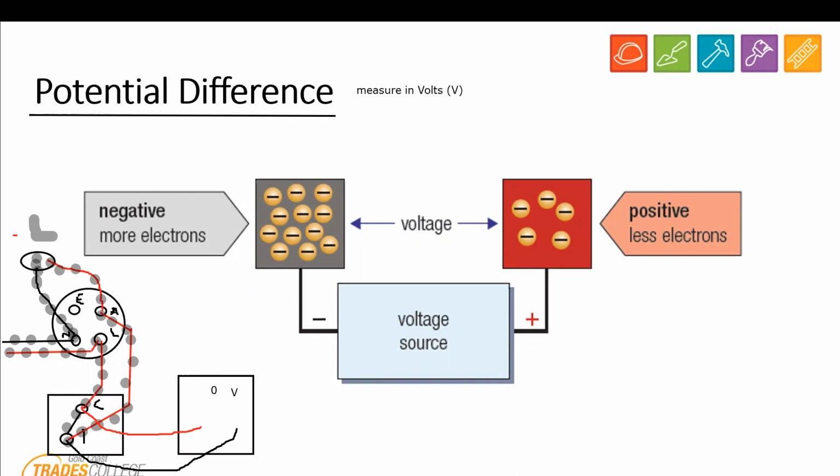Let's get rid of that. Let's get it in black. So I've got 2 voltmeters going on. I've got that one there. I've got voltage at the top. So let's have a look this time. Let's correctly connect it into where I can measure the voltage. So, and excuse the lines crossing each other, but from this point here is where I'm going to put my black lead. All right, so the black lead goes into the neutral, and the red lead needs to go in to either of these points. All right, but let's say for now, this point here.